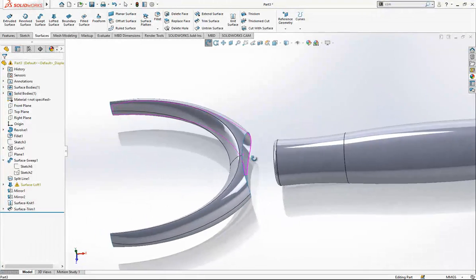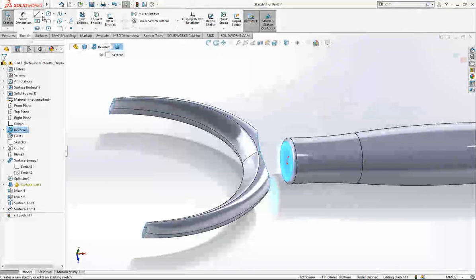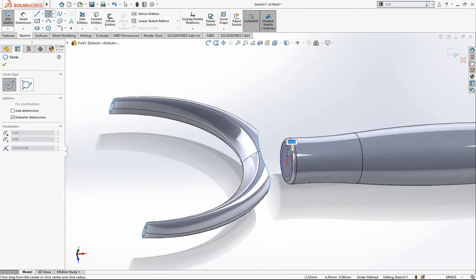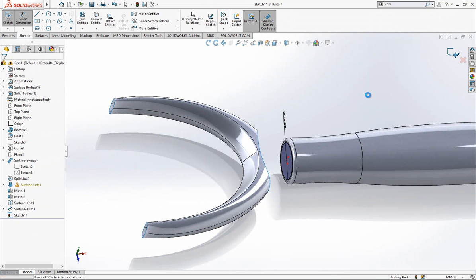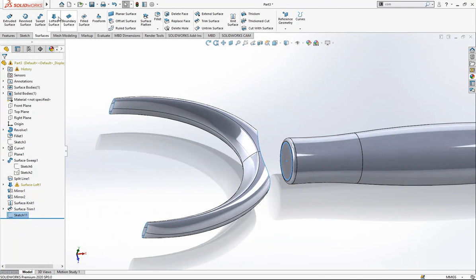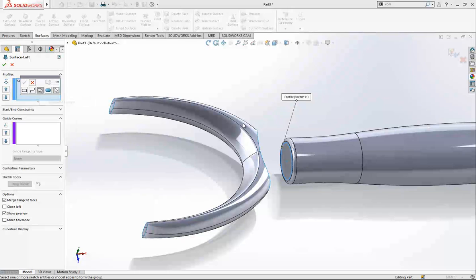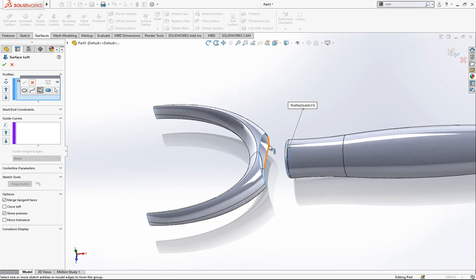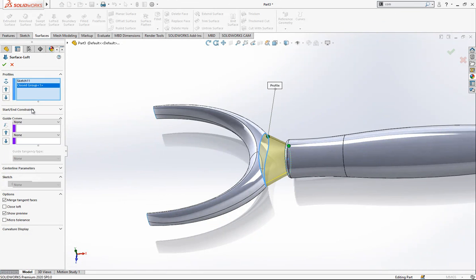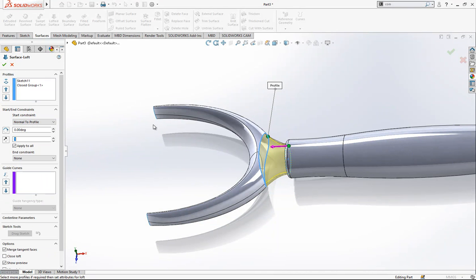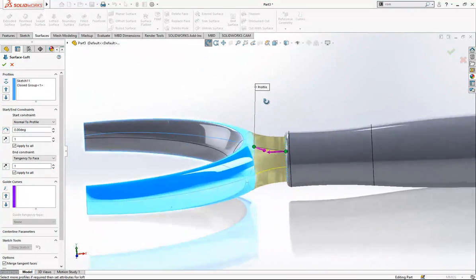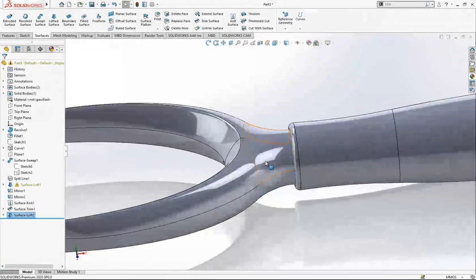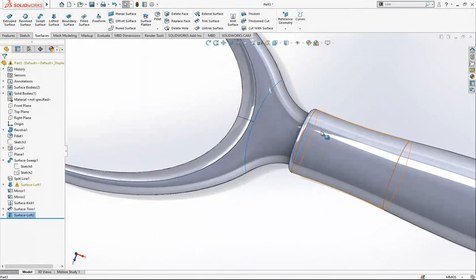And we cut it. And here I'm placing a sketch, a 12mm diameter sketch. From this 12 to this area, we will pass with loft, selection manager, it's good, and sketch normal to profile. This is tangency to face, and it's so nice, a soft connection. We connect our body to our holder.